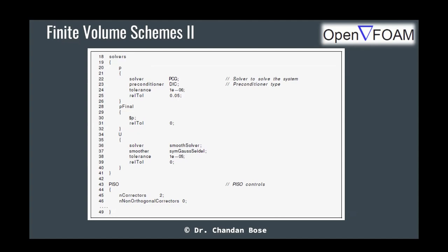So I think ASCII would be a good choice for most of the common problems because normally ASCII files can be converted to different formats as needed. For example, VTK. So if you want to do some post processing with Python and then use ParaView, etc., or convert it to Tecplot equivalents, VTK files are very important to see the flow field visualization, etc. ASCII can be easily converted to VTK.